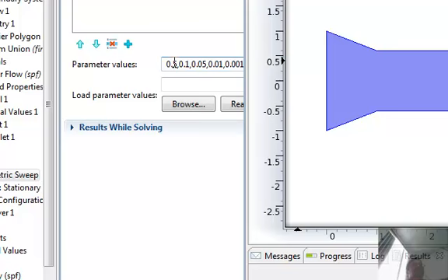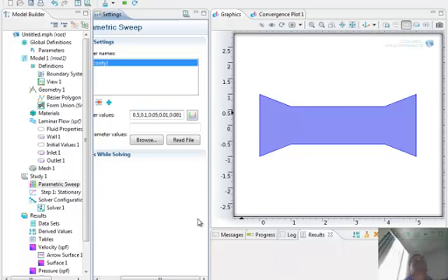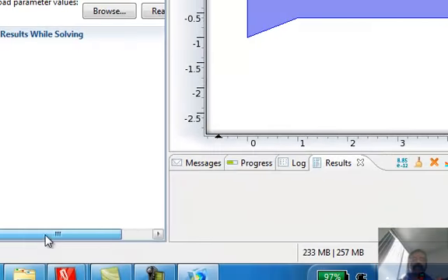Increases. So initially I started with a Reynolds number that's close to 1 because I picked my density 1, viscosity 1, dimensions are of order 1, velocity is 1, right? So my Reynolds number would be somewhere close to 1.5 or something like that. And then from that point I want to double it and then increase it progressively. So what would be the largest magnitude of the Reynolds number that I will be calculating? About 1000, of the order of 1000 or so, if I succeed in getting a solution for all those. Okay? So I have set that up.